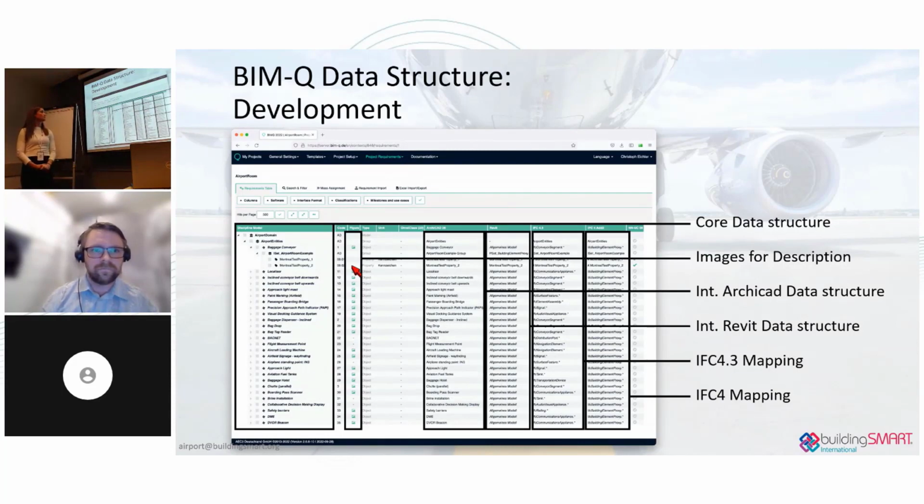In IFC 4, we had to declare a lot of things as building element proxy. It's not good because you can't check the IFC files later on so specifically, because when everything is related to the proxy, it's not possible to have type-related checking. So you have a lot of properties on the proxy. You lose a little bit of control, and with IFC 4.3 we have more specific entities we can use, and we have more user-defined types, but it's much more precise to work like that.